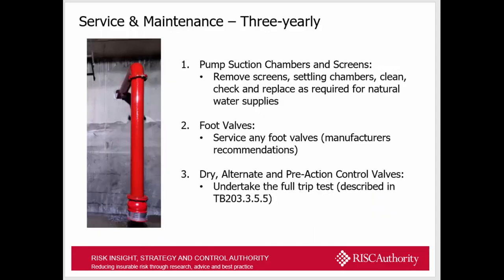Moving on to 3 yearly, so if you have pump suction chamber screens, it's to remove the screens and settling chambers, check, clean and replace for natural water supplies, so canals, riverbeds, etc. Foot valves in any tanks that are below the water supplies: service any foot valves in accordance with the manufacturer's recommendations. And every 3 years on dry, alternate and pre-action control valves you undertake a full trip test as described in Technical Bulletin TB 203.